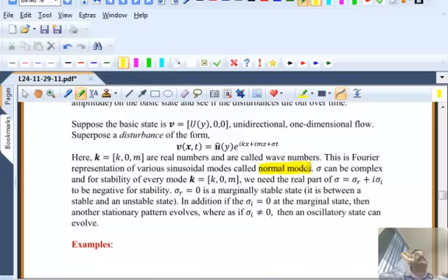Remember, when we talked about the Poiseuille flow in a pipe, I said that the flow becomes unstable around Reynolds number of 2100. Where does the disturbance come from? The disturbance comes from your pump, from any vibrations in the lab. Small disturbances can trigger that. I've also told you that there are experiments conducted recently where they removed all the sources of perturbations, and they were able to maintain the laminar, parabolic flow for Reynolds number as high as 100,000. Okay? So it is the small perturbations that cause the flow to become spontaneously unstable.